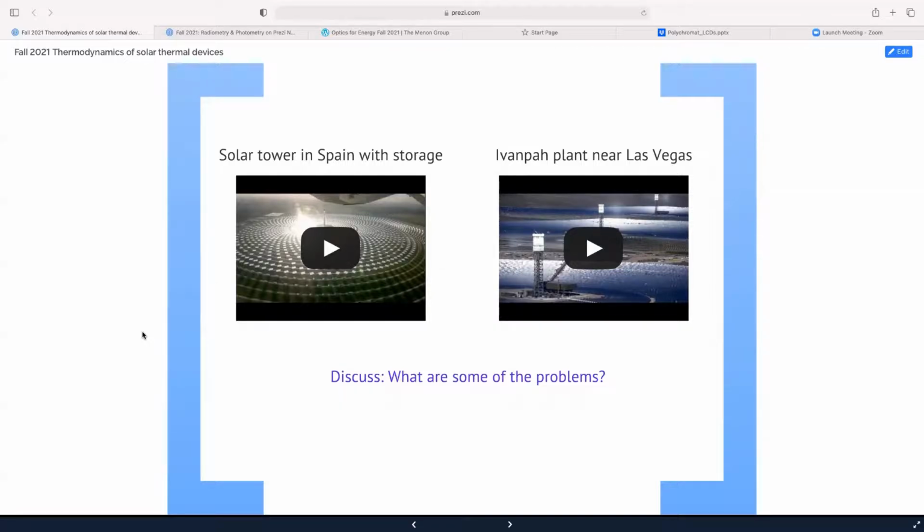Yes, that's a good point. It's a very good point, actually. Kelsey mentioned the molten salt will lose heat very quickly. That is the radiative losses we talked about, on the absorber, the TH we talked about. And of course, insulation is important. Also, molten salt is incredibly corrosive, so you have a material science problem of how to actually store it. I don't know enough about it, but it's definitely an important problem.